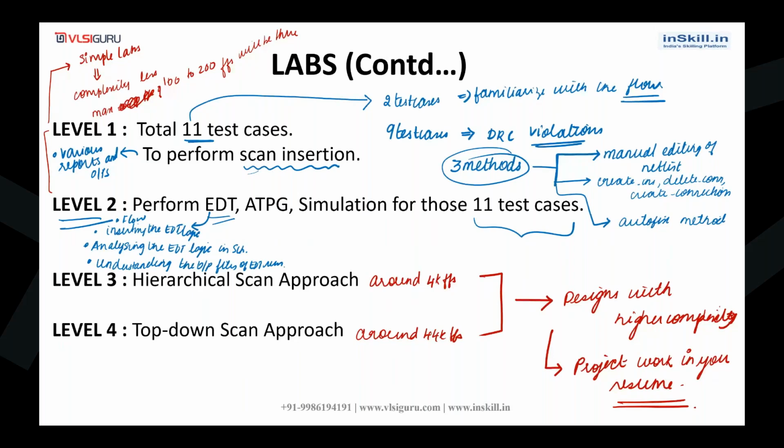Again, in ATPG also, we will be understanding the flow of ATPG, and the practicals will be done for these fault models: stuck at fault model, transition delay fault model, and IDDQ fault model. We will be doing the pattern generation for these fault models in our labs.